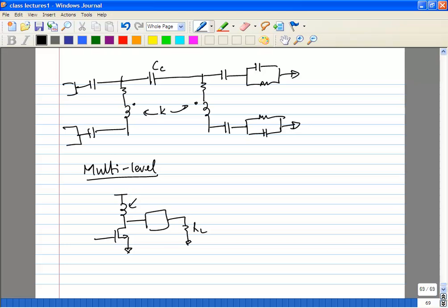What you're actually using it for is, what property of the inductor do you know about? It doesn't allow current to change suddenly. So if you have a very large inductor, it tends to have the same current. Effectively, it is offering a DC bias. It's biasing the output at VDD, but it is also keeping the current through itself stable.